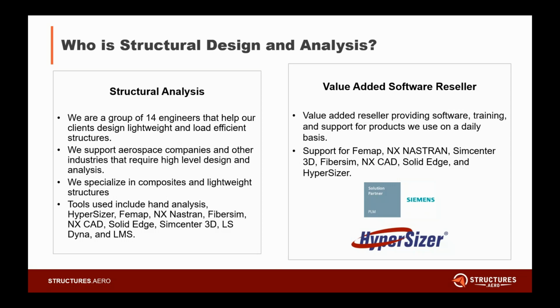And then the last question is, what are typical values for elements passed for various element types for MSC Nastran? I think Nastran calculates it differently, and we could summarize that as well in a follow-up. Yeah, I think that goes back to what I was saying about Femap inverting, or it's the reciprocal of the number. It's numerically the same value, just Femap displays it differently. I think that it displays the reciprocal. Right.